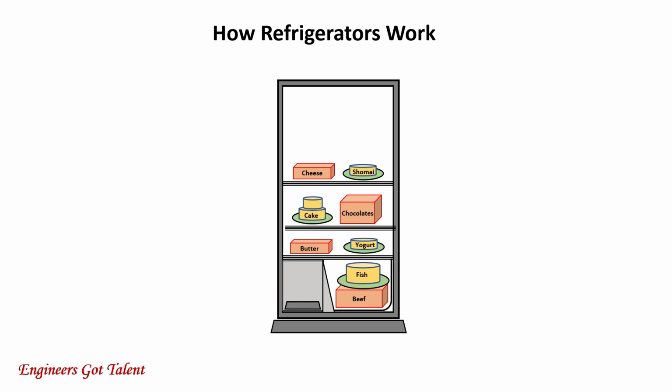In residential or commercial air conditioning, the purpose of refrigeration is to collect the heat from the rooms, heat from the occupants of the building, and then dump them somewhere safe. Inside your refrigerator, the compressor is located at the bottom of the fridge, and its job is to increase the refrigerant pressure and temperature. The compressor is also responsible for circulating the refrigerant around the system.